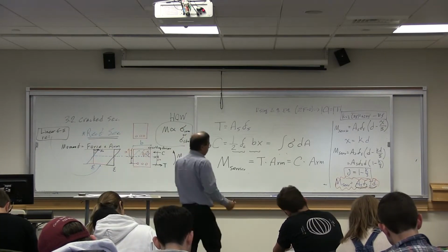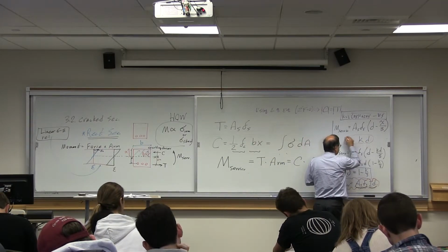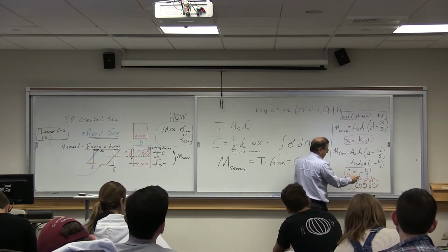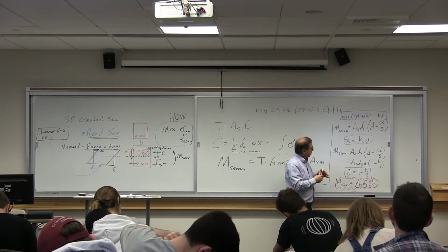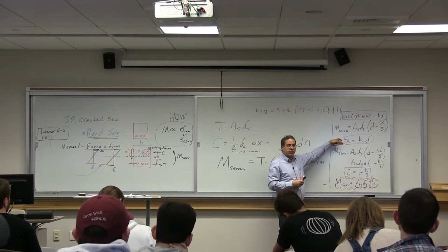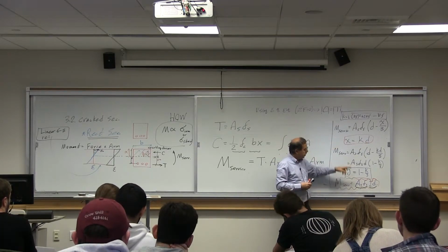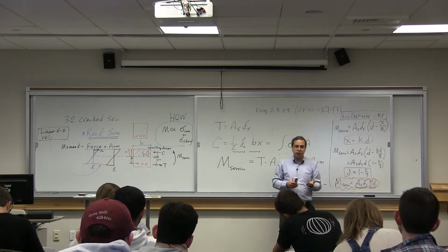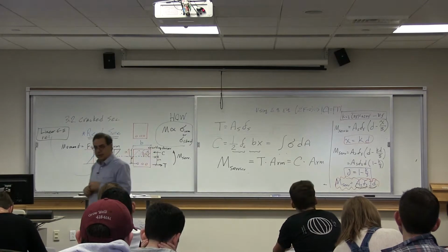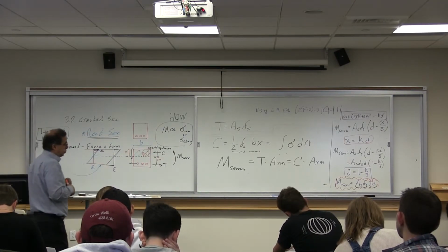The reason these terms are defined, you can see a parallel here. Both k and j are related to d. k times d gives you the depth of the compressive zone. j times d gives you the arm. Those are two changes of variables or parameters we often use. You can see in concrete books that they are used.